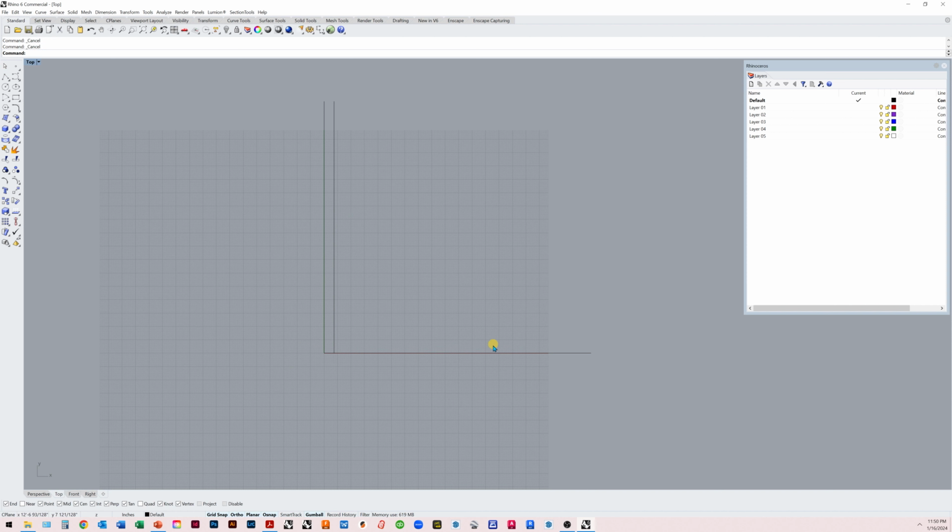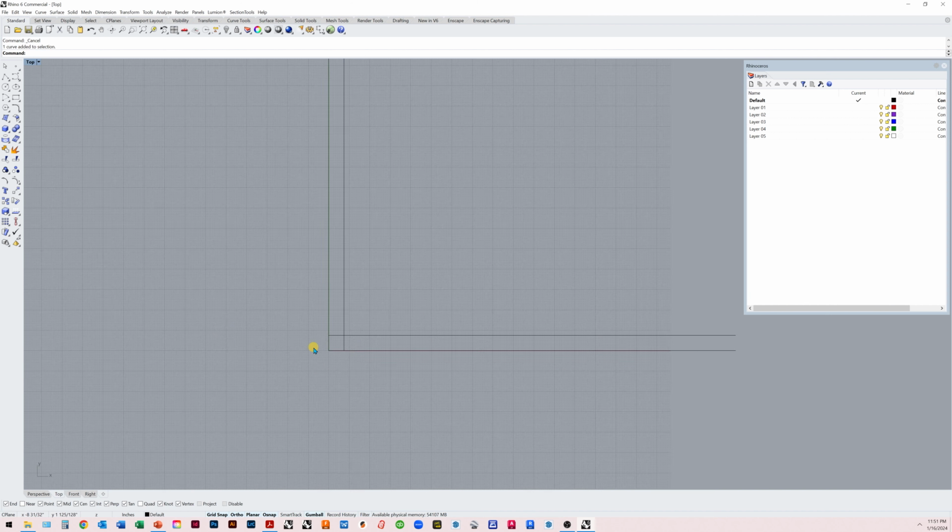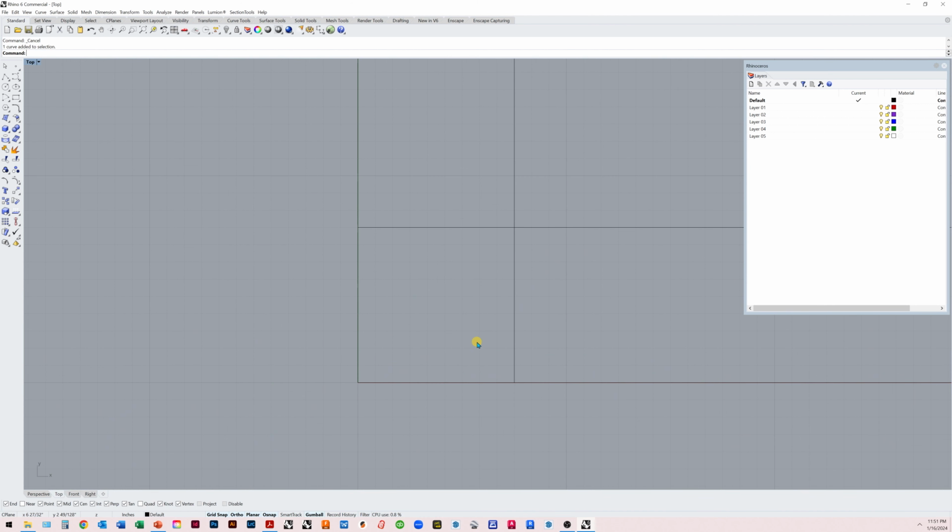All right, so let's do the same thing on this bottom line. Let's right click over copy. We could also type the word copy, and then if you look up here, we could click in place, and it would make a copy in place. So now there's two lines there, and if I click on it, you can see there's two lines. And then I'll take that other element, type in 9 inches, and now I have two lines that are 9 inches apart. And if I zoom all the way back in here, this is my 9-inch by 9-inch grid.